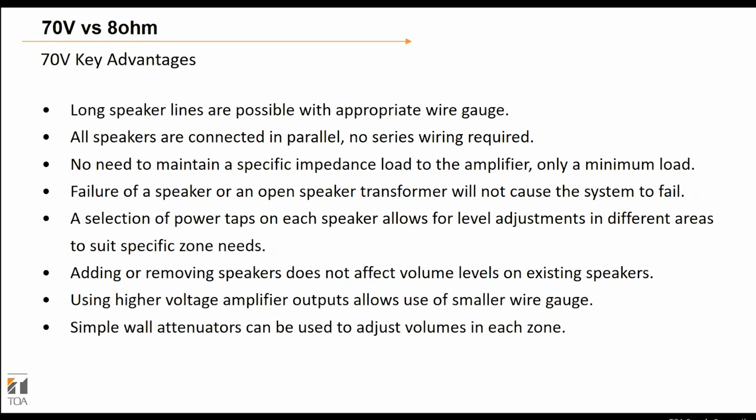The failure of a speaker or an open speaker transformer is not going to cause the system to fail. That is because we are wiring in parallel and not in series. Just like a string of Christmas lights, if your system is wired in series and you have a speaker failure, well, you're going to have the entire system fail. Whereas if you're running in parallel, you don't have that concern. And so 70 volt is always run in parallel, so we never have the issue where one speaker can cause an entire system to fail.